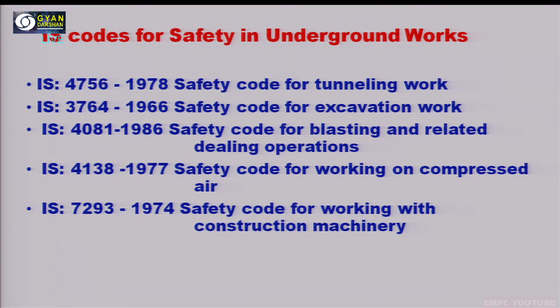Then IS 4081 1986, the safety code for blasting and related drilling operations. Because during tunneling or excavation in some rocky area, we need to blast to loosen the rocks so that we can easily cut these rocks or remove the large boulders, for making a path for our tunnel or the excavation work.